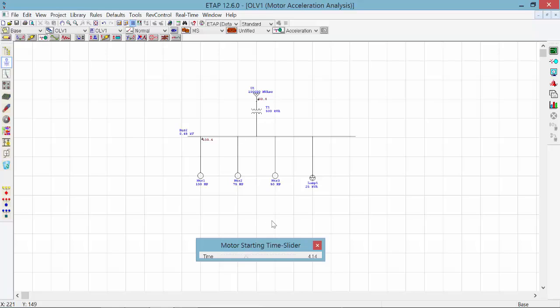So now that we saw an example of the dynamic motor start analysis, we see that we are still in the inrush moment. We are still inside the marginal mode. That's why we use equipment like variable frequency drives in order to control that inrush and the voltage dip on the bus that the load and motor are connected to, which we are going to talk about in future episodes, and in examples and other projects that we're going to take a look at together.